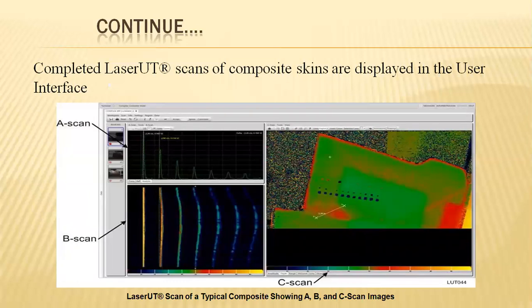So the results are captured at a micro level, showing the internal structures of the walls as displayed in the user interface. The deviations that occur are displayed with respect to heights, peaks and bulging, deformations, and crack growth or grain growth. Upon scanning, these can be clearly observed. And this is the A-scan process, this is the B-scan process, and this is the C-scan process.